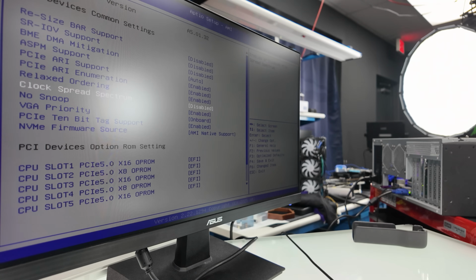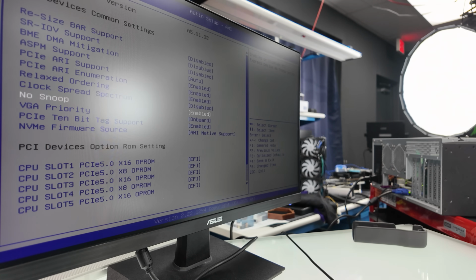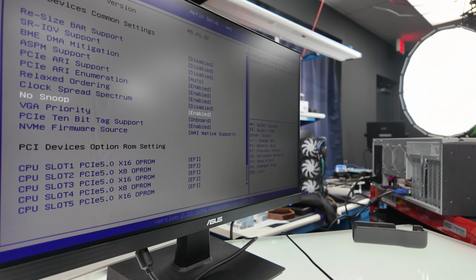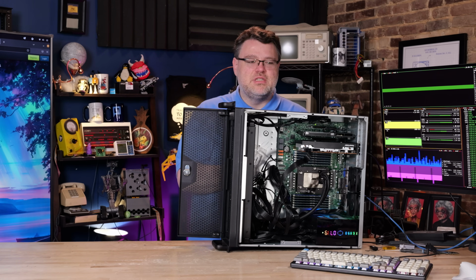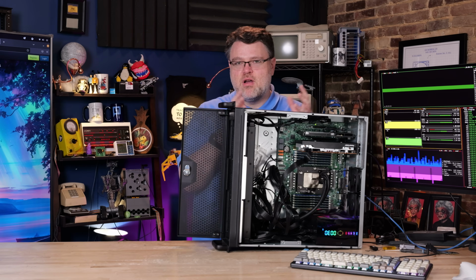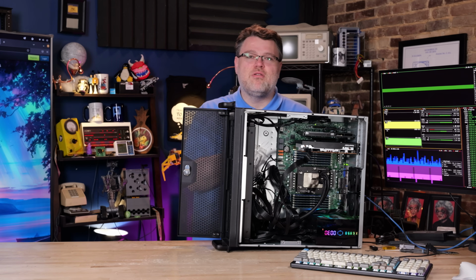And in doing that, it's handy to be able to fiddle with the Infinity Fabric clock, maybe some of the memory power states and some other tunables like that, because DDR5 and the Fabric can clock dynamically for power saving. Heck, with the dual CCD links, I mean, this is a single socket system, but with the dual CCD links and everything else that's going on in the system, you can put more power or less power.